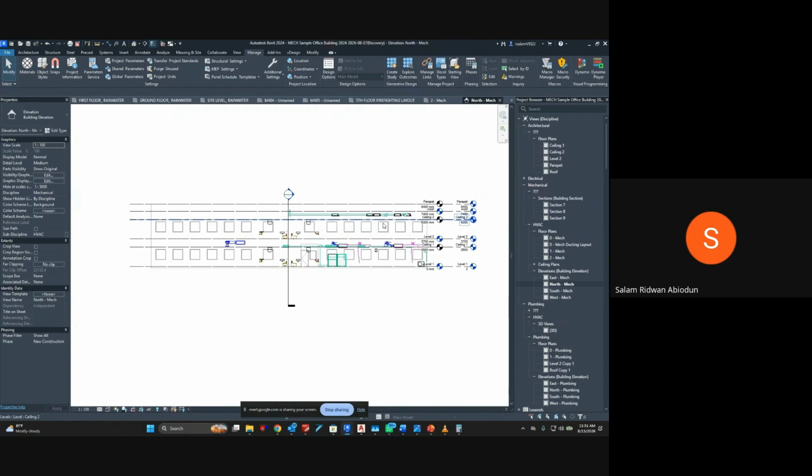Okay, so what I was asking is, has anyone introduced you to creating ceiling plans? Have you worked on a ceiling plan before? On this project, you've not worked on any ceiling plan. Because we are going to be hosting those sprinklers to the ceiling, actually. The reference plane, the ceiling. Most of the equipment are not hosted, so we can select any level for it.